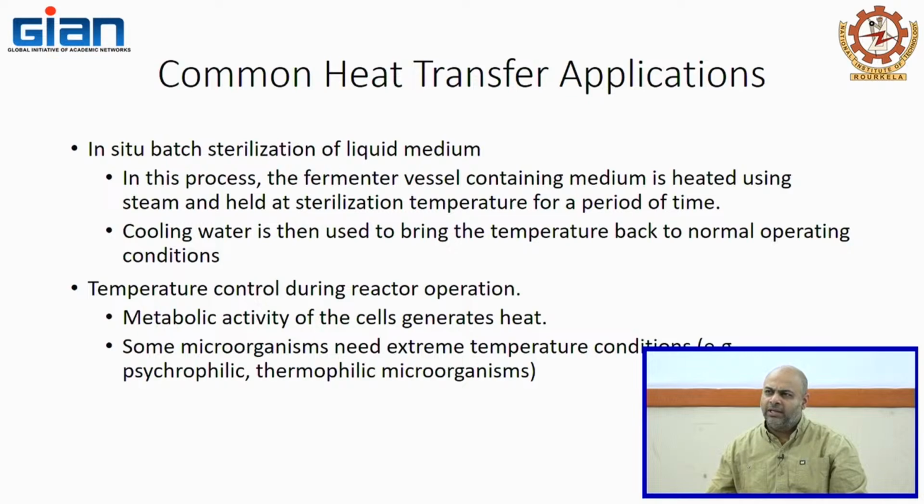Now, when you are maintaining these types of organisms, how will you work with your oxygen transport? That will also change. Depending on the temperature of the medium, the oxygen transport rates will also change. So, depending on the organism, we are looking at the OTR. You study the organism, find out what OTR they require, and only then you build the rest of the system on that.